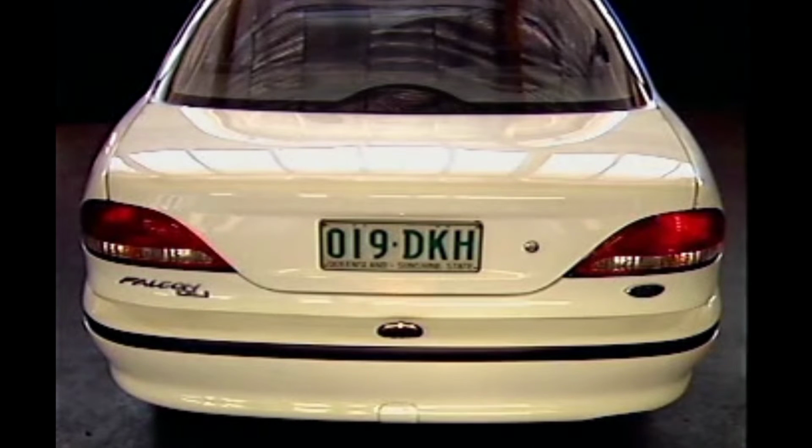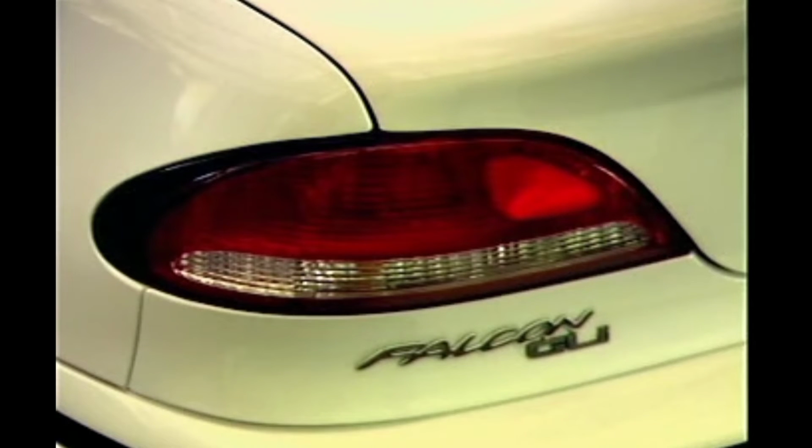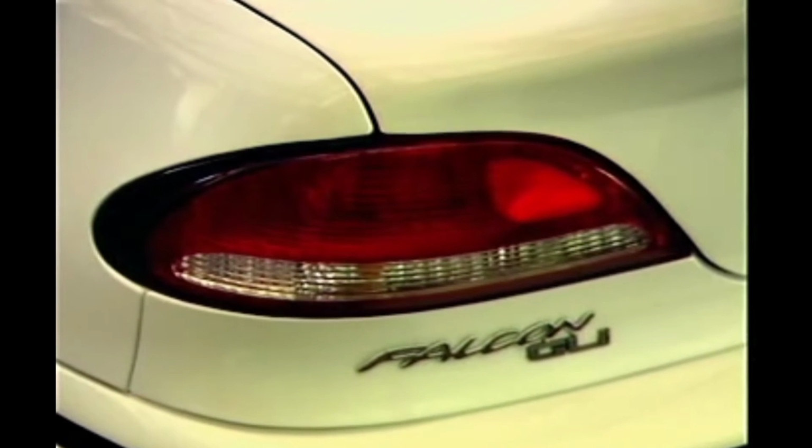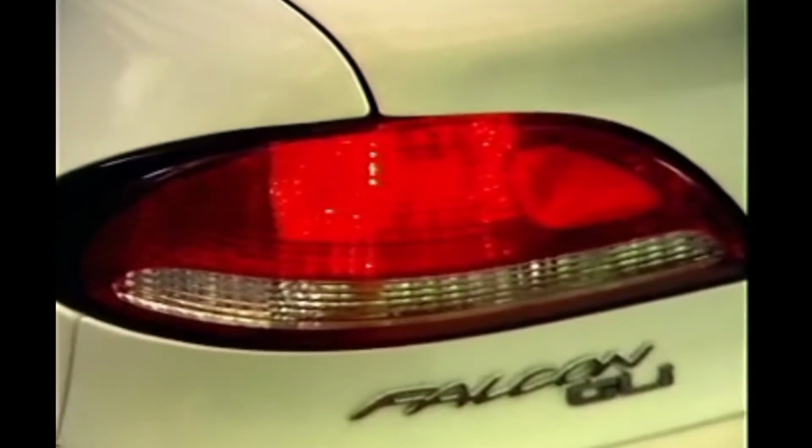The bulbs are connected in parallel to each other so that the failure of one filament will not cause total circuit failure. A number plate illumination lamp is usually connected in parallel to the tail lights and operates whenever the tail lights are on. The tail lights are usually incorporated in a cluster assembly at the rear of the vehicle. Government regulations control the height of the lamps and their brightness.